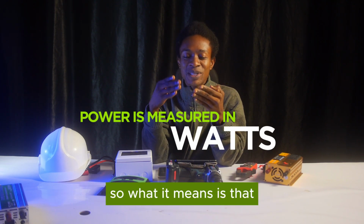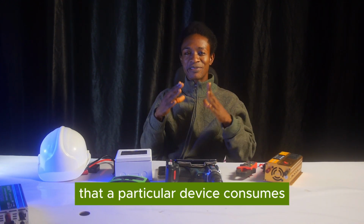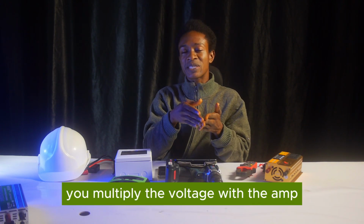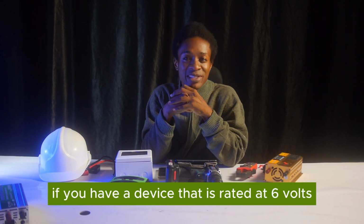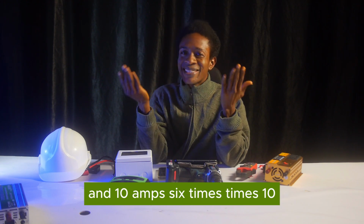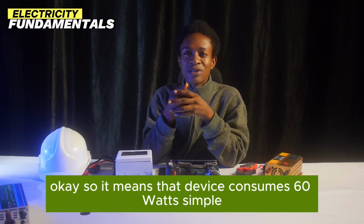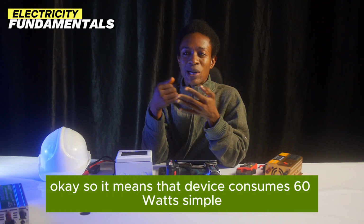So what it means is that if you want to calculate the amount of watts that a particular device consumes, then you take the voltage and the amps. You multiply the voltage with the amps and it will give you the wattage. For example, if you have a device that is rated as 6 volts and 10 amps, 6 times 10 gives you 60. So it means that device consumes 60 watts.